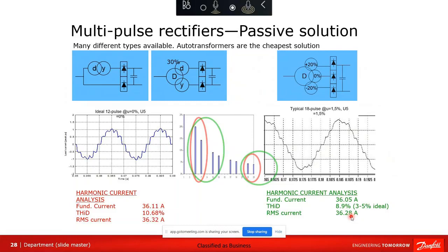A couple of downsides. Number one, this little gizmo right here is known as a phase shifting transformer. So I take 3 wires in, line 1, line 2, line 3, and I take 9 wires out. This is a rectifier bridge, this is a rectifier bridge, and this is a rectifier bridge. The phase shifting transformer is not exactly miniature. It's fairly large, generates heat, and needs to sit in a bigger cabinet.